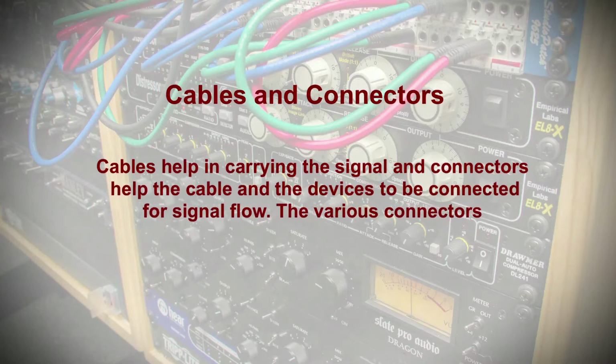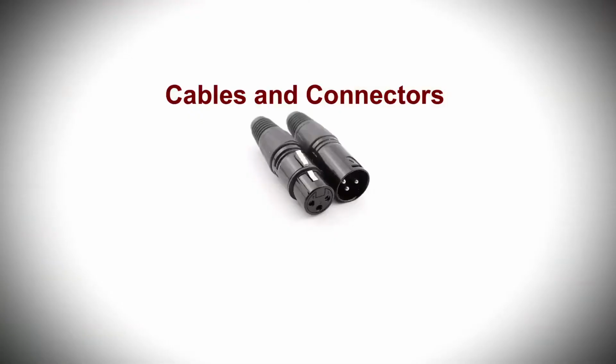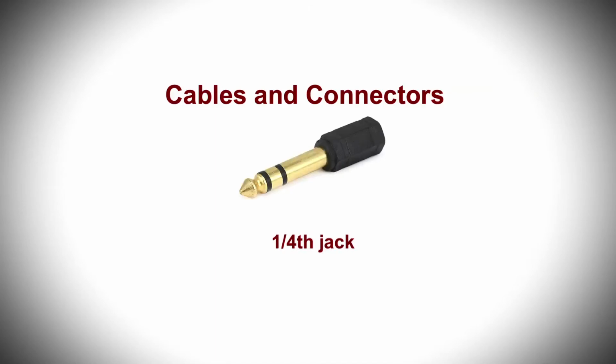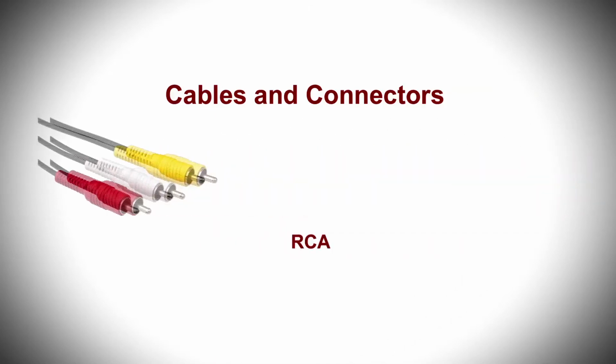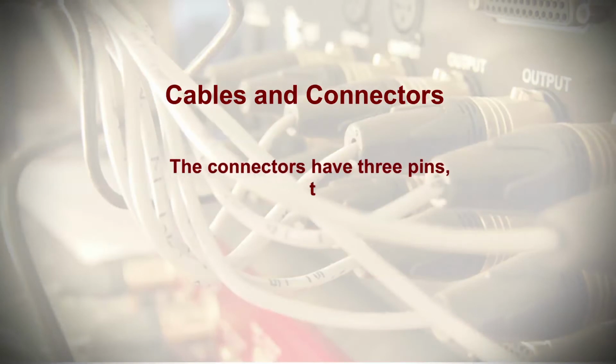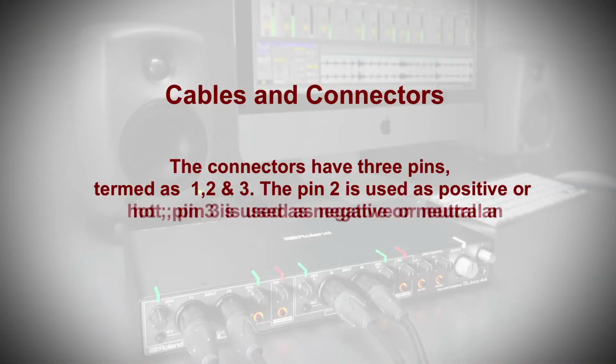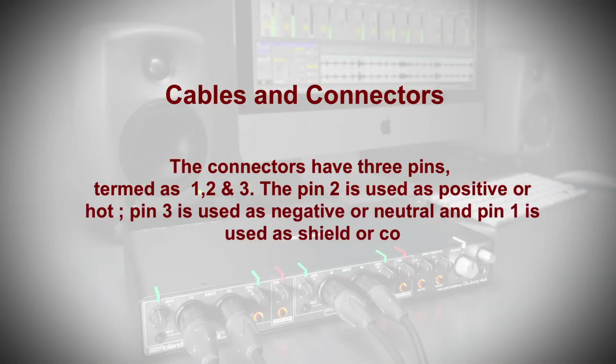The various connectors used in an audio recording studio are auxiliary, male and female, 1/4 inch jack pin, RCA, EP jack pin. The connectors have 3 pins termed as 1, 2 and 3. Pin 2 is used as positive or hot, pin 3 is used as negative or neutral and pin 1 is used as shield or common.